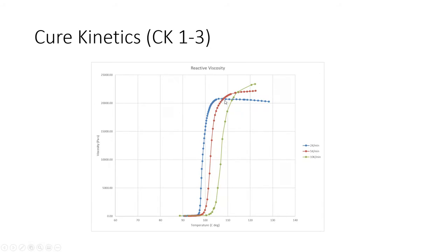We would normalize these curves and call the x-axis 0 to 100 percent degree. Moldflow requires you to input this data that way, whereas Moldex3D and SigmaSoft require you to input this information in terms of percentage cure.